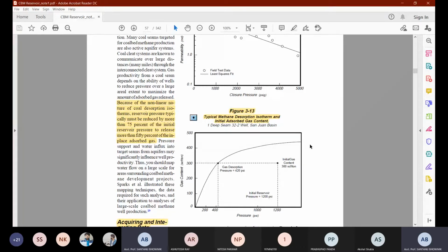That means suppose you are going to measure the same coal and you get 0.5% porosity or maybe 2% porosity. It is not the case that after some time, if you are not doing anything, you will find that the volume has increased and it is showing 5% porosity. No, unless you change its structure, or it is under some chemical condition, its porosity is a physical property. It is not going to change. That's like the density.